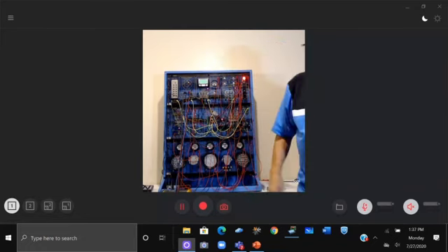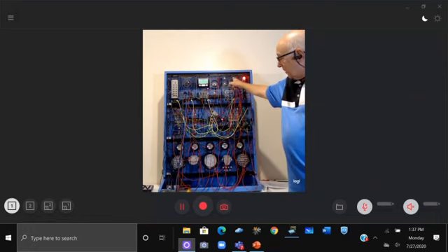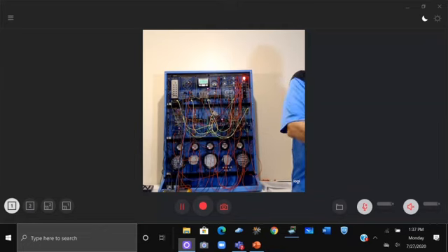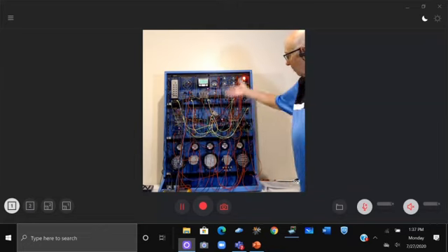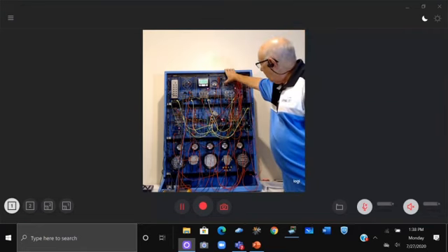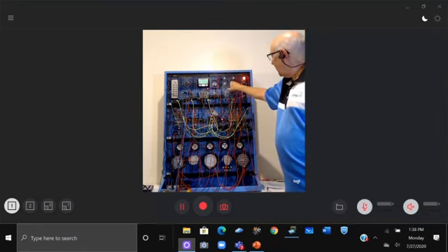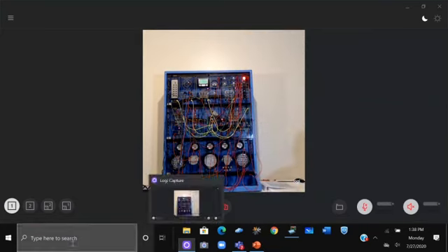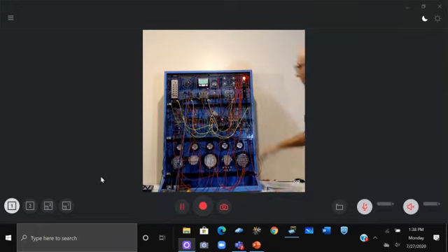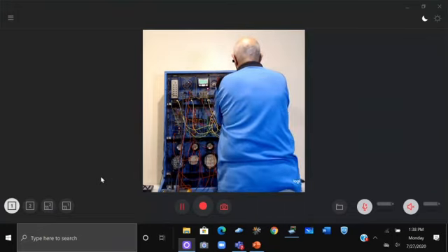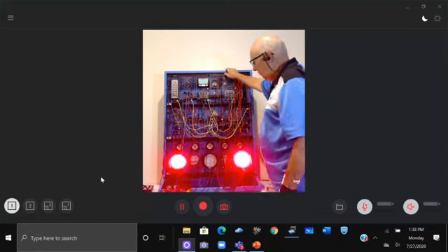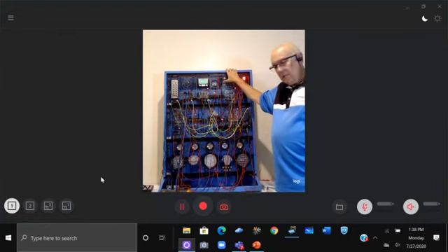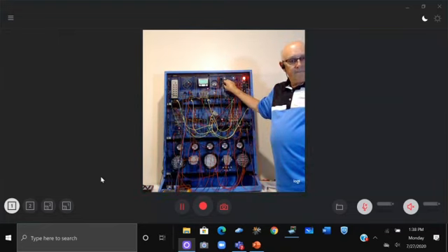Okay, now, I just turned on the backup light. Notice, backup light doesn't work. In other words, whatever this problem is, it has shut down a module. Does anything work? Doesn't look like anything works. So it has shut down the whole system. That's what this error did to it, okay? Because if we get rid of the error, brake lights, okay?